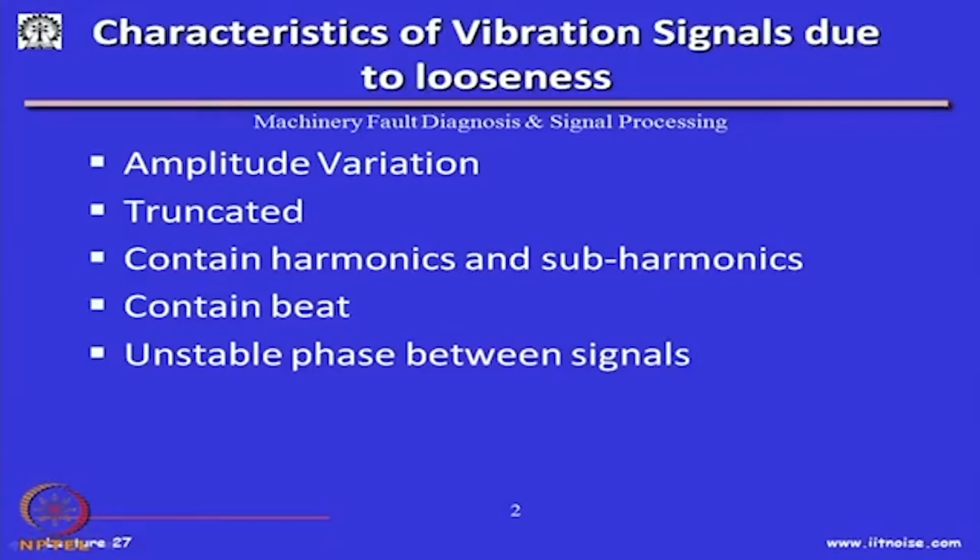The characteristics of vibration signals due to looseness: there will be significant amplitude variation. These signals in the time domain would look truncated. I will explain one of them. They will have certain harmonics and subharmonics, and then there could be a beating of the signals and unstable phase between signals. So, we will see each one of them one by one.